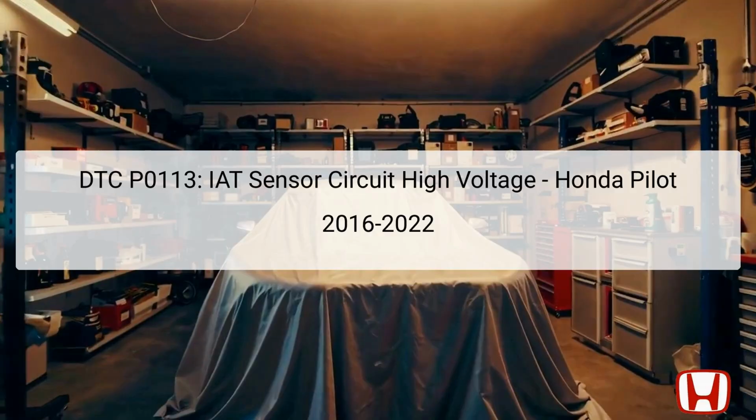The diagnostic trouble code, DTC P0113, indicates an issue with the intake air temperature IAT sensor circuit, specifically pointing to high voltage in its reading. This code is crucial as it helps the engine control module, ECM, manage engine performance effectively by monitoring the air temperature entering the engine. The IAT sensor is typically located in the air intake duct or as part of the mass airflow (MAF) sensor assembly, where it measures the temperature of the incoming air.